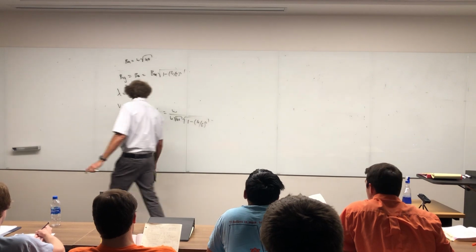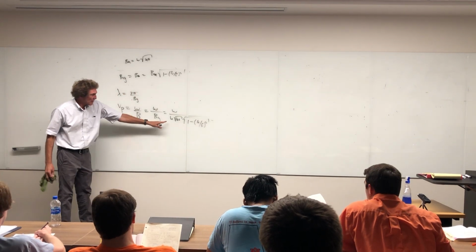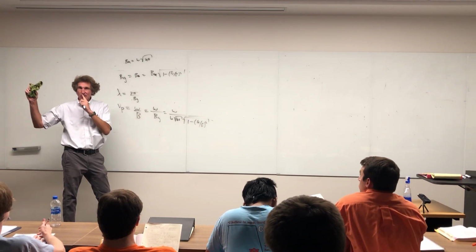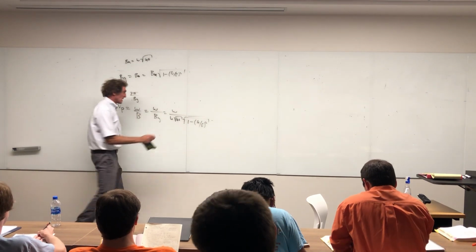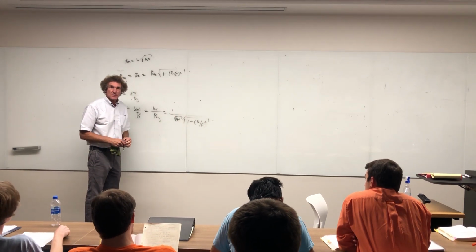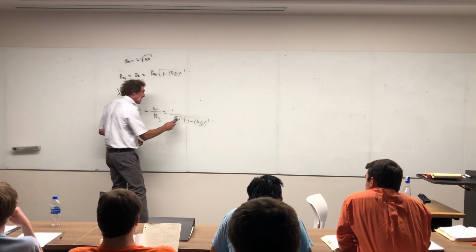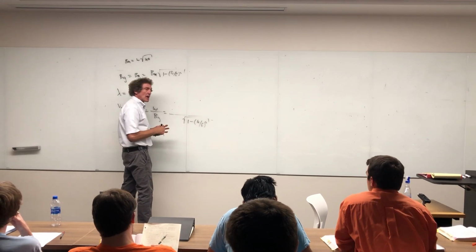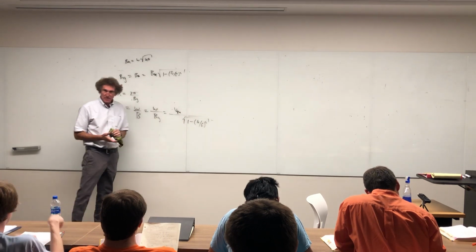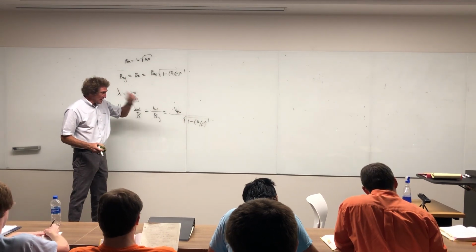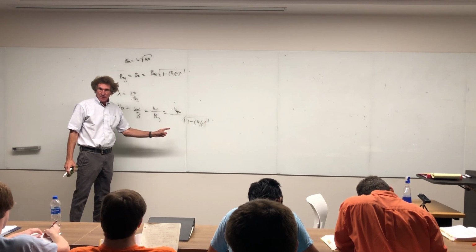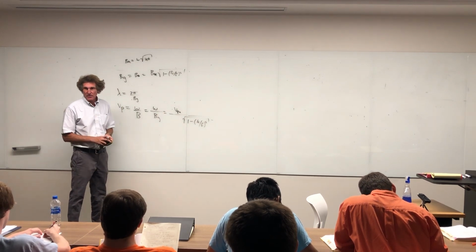What do you notice about this equation? Well, how many see that the omegas cancel? That's the starter. Do you all agree with that? Second thing is, what is 1 over the square root of mu epsilon? It's really the velocity in an unbound region, right? So it'd be the phase velocity in an unbound region. Now, what happens to that velocity as you approach cutoff? It's tending to infinity, right?